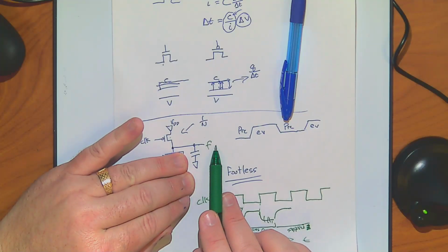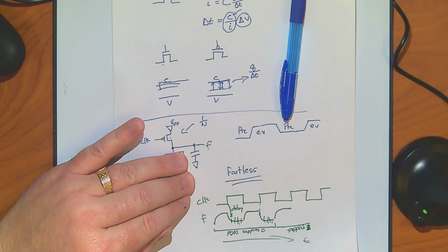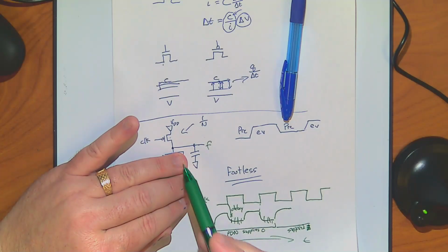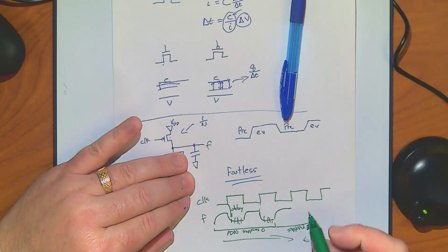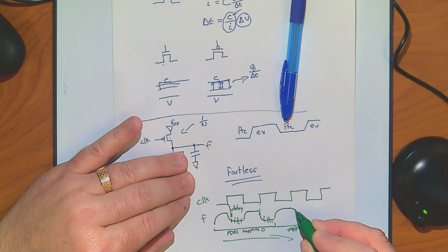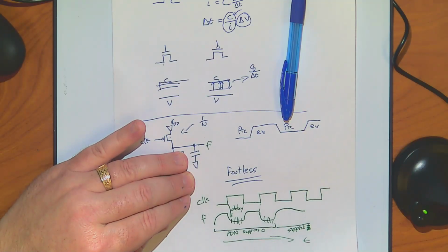That means this capacitor is now supplying out here to the system. That outer system shouldn't be a heavy draw on it if you design your logic right, and that's what we're trying to do here. It doesn't take a lot to do these. So I have to make sure this capacitance is sufficient, but assuming it is, it's going to have a very slow drain. So it is a downward curve, but with a much different time constant because the system on it isn't as demanding as this one was. So it's going to stay in the 1 zone. It is dropping, but it can't drop forever.